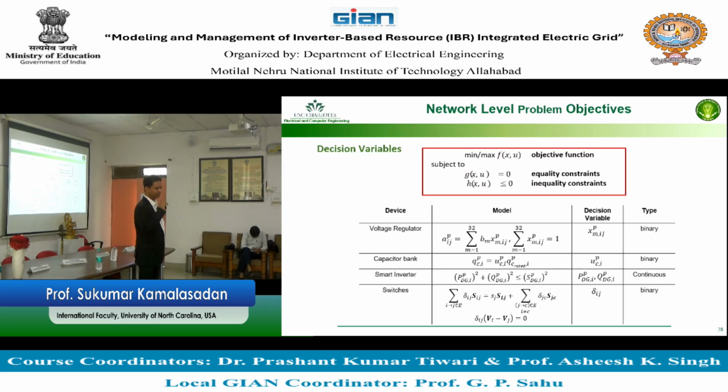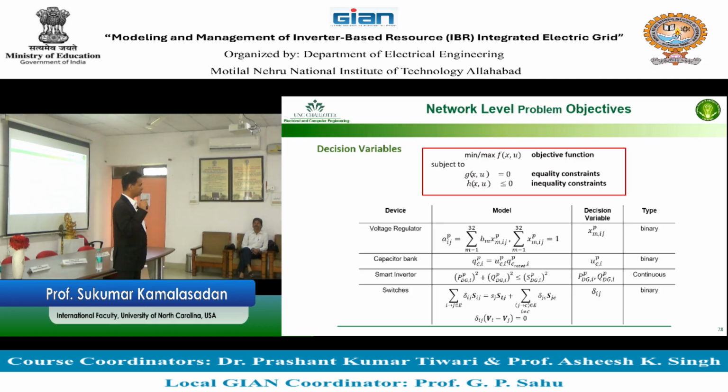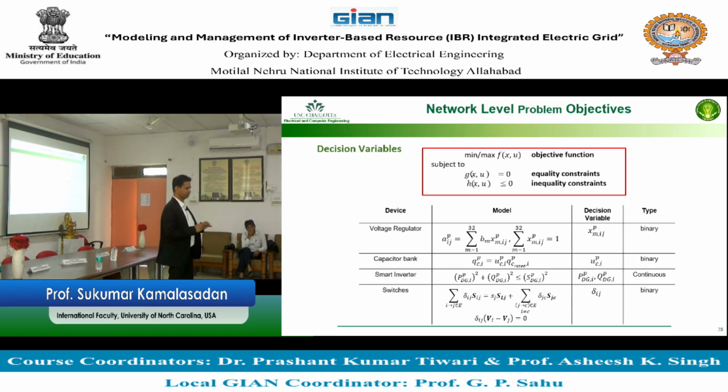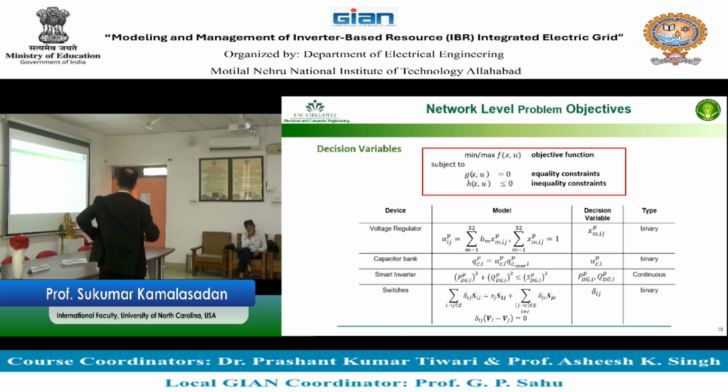So this is a general form. Discrete set point controllers are also called regulators in the control theory world. If you wanted to regulate water in a tank, it's a regulator. What a regulator does is look at the level and then go to that level. Continuous set point controllers are generally called tracking. For example, with machines, you don't do regulation; you track speed or whatever. Tracking is a big deal, meaning it's not that easy to do. And for the on-off controller, you say, turn it on or turn it off.